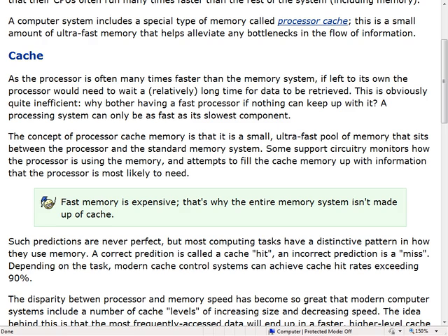The typical sort of memory that you get on computers is dynamic memory. That's memory that has to constantly refresh itself, and being able to access it is a little bit more difficult than with static memory. You'll hear about cache SRAM, static random access memory, and DRAM, dynamic random access memory. The type of memory in most memory modules these days is called SDRAM. In that case, the S doesn't stand for static. It's not static dynamic random access memory, because that just doesn't make any sense. The S in that case refers to synchronous, and that's all to do with the timings of how the memory interacts with whatever it's connected to.